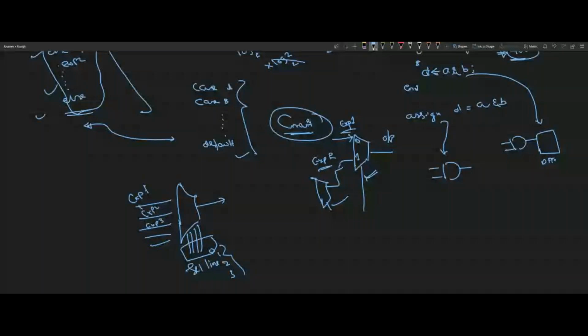A task is only simulatable. It cannot be synthesized, and we especially use it for bus functional model creation. It can have sequential behavior, I mean you can have a clock in the task. Whereas a function is synthesizable, but it cannot be used for sequential logic. For instance, if you want to create a multiplexer or some gates, then we use functions. So the difference between task and function is very important. Also Mealy and Moore machines, the FSM types, they ask, and blocking and non-blocking.